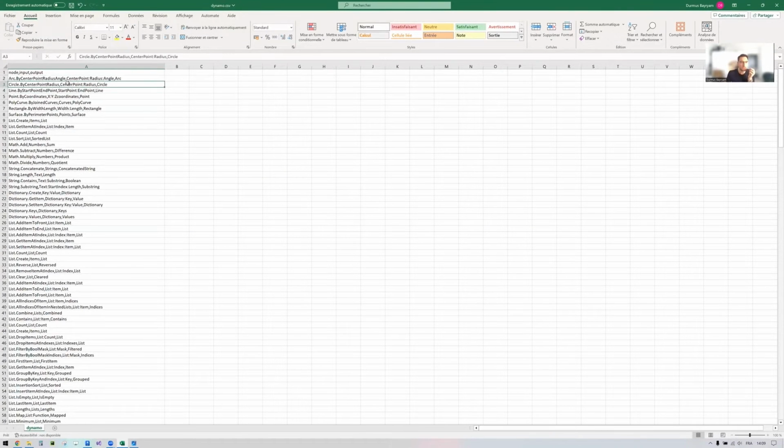If I give a node, for example, here as one, it says that you can obtain a radius using our B point. That is, you need a center point, its diameter, and the output will be a circle. But if this circle node is in your scenario, other geometry nodes must continue in connection with the circle. All this input-output relationship is learned by Dynamo, and at the end of the day, it suggests to us that if you use this node, look, all these nodes related to other Dynamo nodes are also connected. You have a choice of which of these nodes to use.